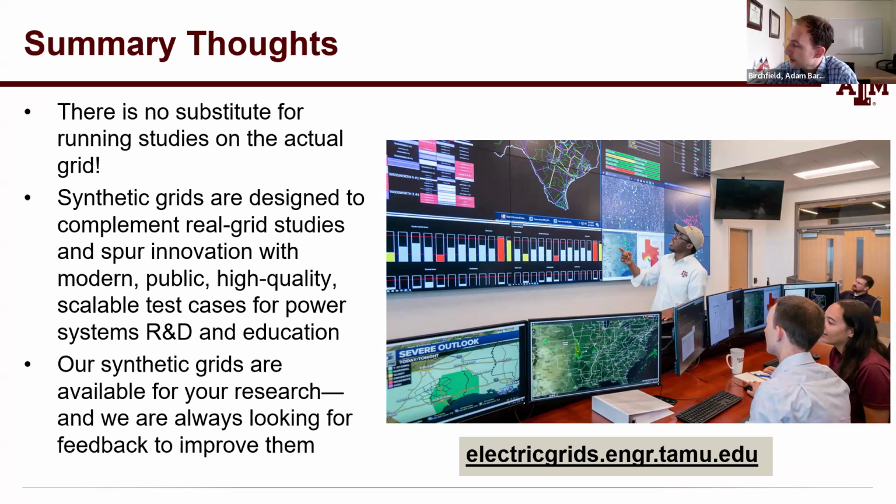But time domain transient stability modeling is a fairly general stability analysis technique, which has the capability to analyze various phenomena, including frequency stability, as well as angle stability, and to some extent, dynamic voltage stability, by just having models that are appropriate for the time scale of milliseconds to seconds. So definitely that is something that this model is capable of studying.